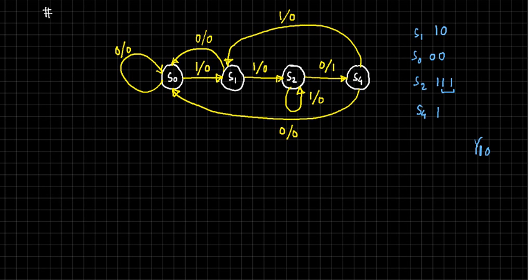Yeah, first we'll have to determine the number of states, then the number of flip flops required, then which flip flop to use. We can use any flip flop. You remember? We can use any flip flop. After that we'll determine what inputs are required for the desired output, and accordingly we will prepare the tables of inputs, the present state and the next state. You remember those tables? The present state and next state.